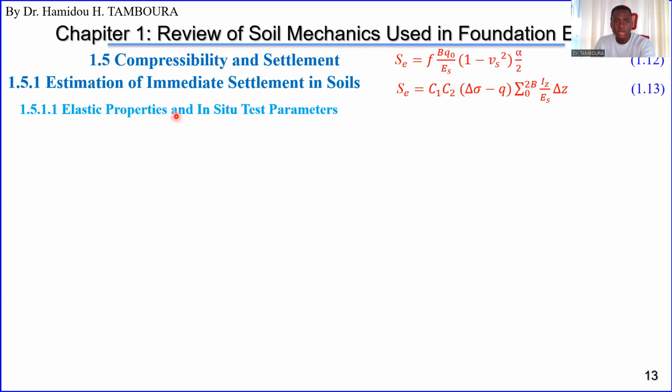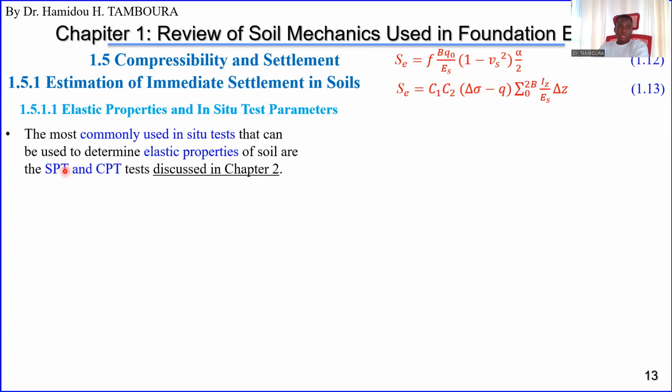Now we are talking about elastic properties and in situ test parameters. As I said, the main difficulty is obtaining the Young modulus, the elastic modulus of soil. So sometimes people use in situ tests to obtain it. The most commonly used in situ tests are CPT and SPT, which will be discussed in detail in chapter 2.